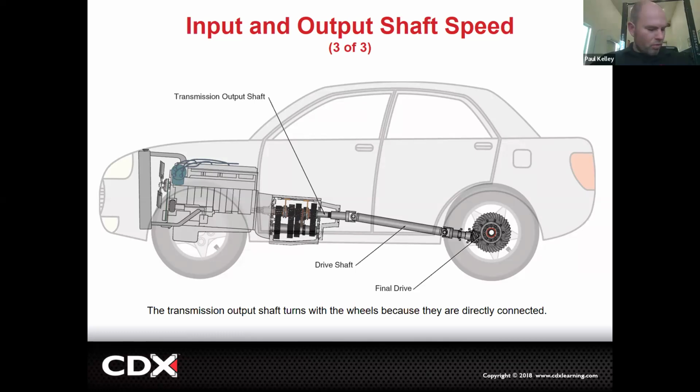But I want to break it down a little bit more. When we think about the clutch, remember, by default, the pressure plate is squeezing the clutch, so it's engaged. Only when we push the pedal down are we disengaging it, right? So as soon as you find a clutch is not disengaging all the way, it's generally going to be a problem with the release system. Does that make sense? The whole clutch master, slave cylinder, clutch line, fluid, air, all that type of stuff, that's all got to do with the clutch disengaging.